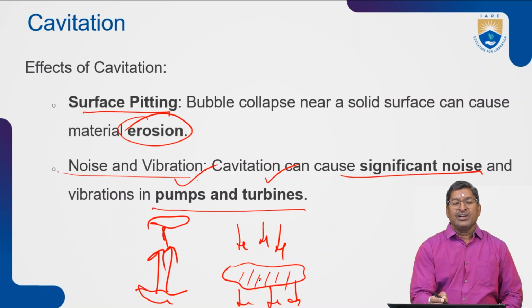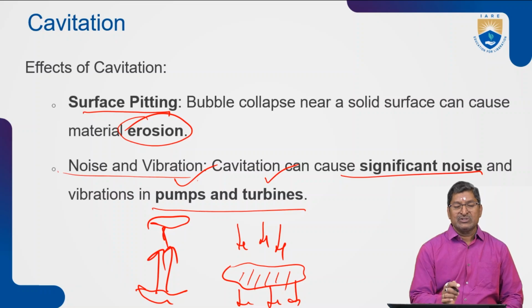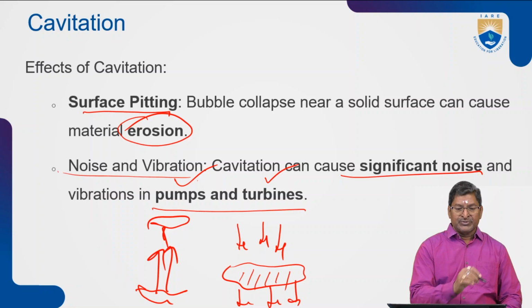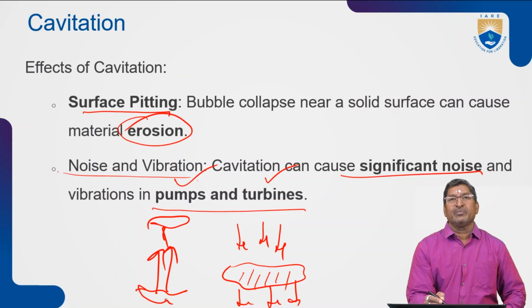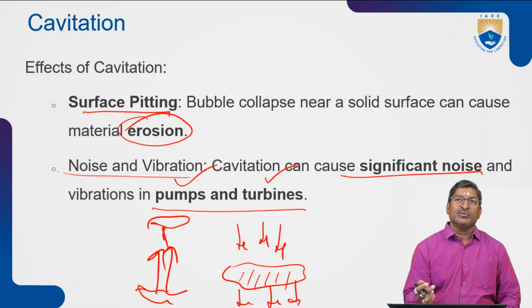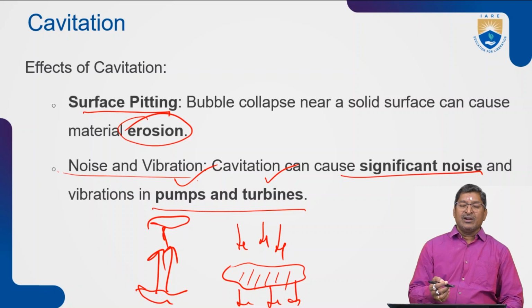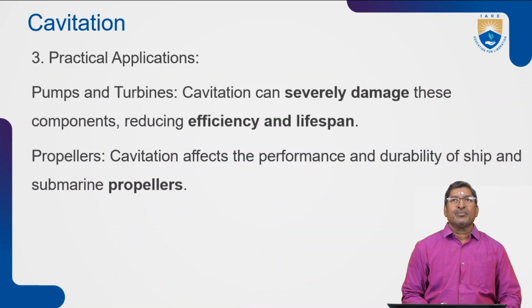In a pump, the rotating part raises water to higher levels. So both of these will get cavitation at low pressures, at the propeller and impeller. Impeller means it is in pumps, and propeller means in turbines. Whenever low pressure occurs at the impeller or propeller, bubbles will form immediately. After getting high pressure, these bubbles will collapse, make noise and also erode the material of the impeller or propeller.